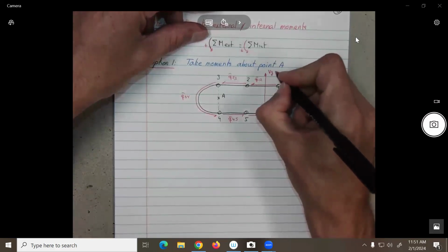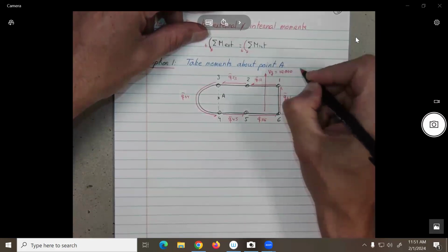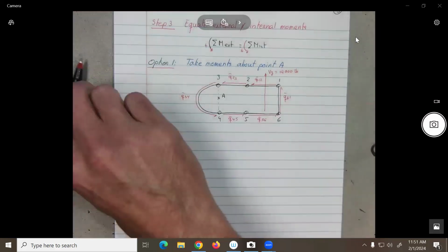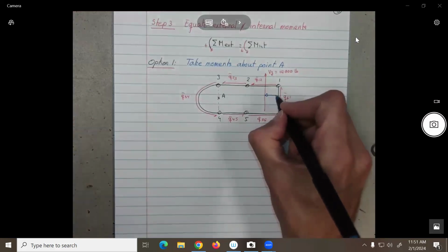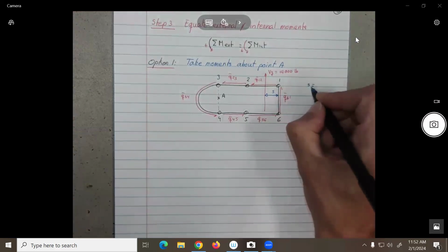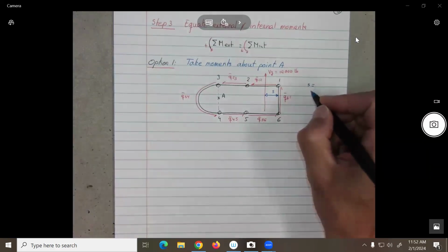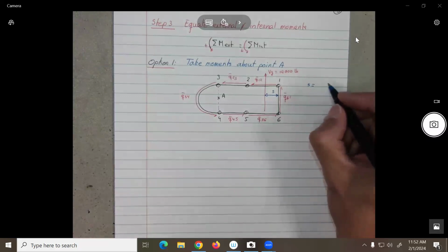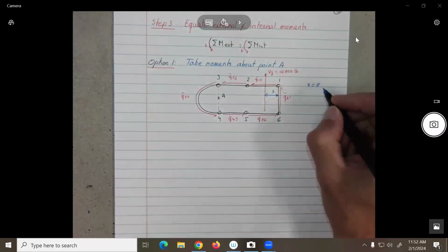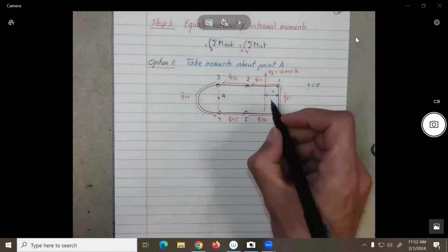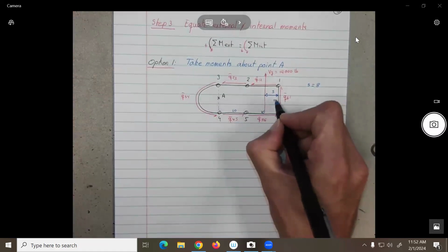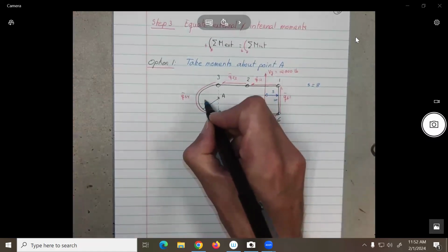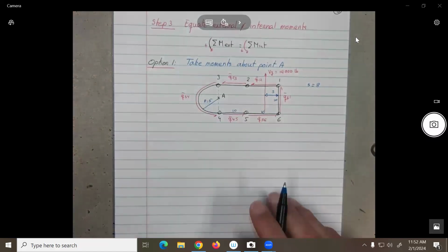And then remember now for the external, we need to add the force over here, the shear force Vy equal to 10,000 pounds. Then what do we know? That distance here was S. S was equal to what on the initial problem? I think it was 8, no? Is it 8? Yeah, 8. And then we basically know that all the other dimensions are like 10, no? This is 10, this is 10, and this is 10 over here, and this over here is equal to 5. Obviously, it needs to be equal to 5.